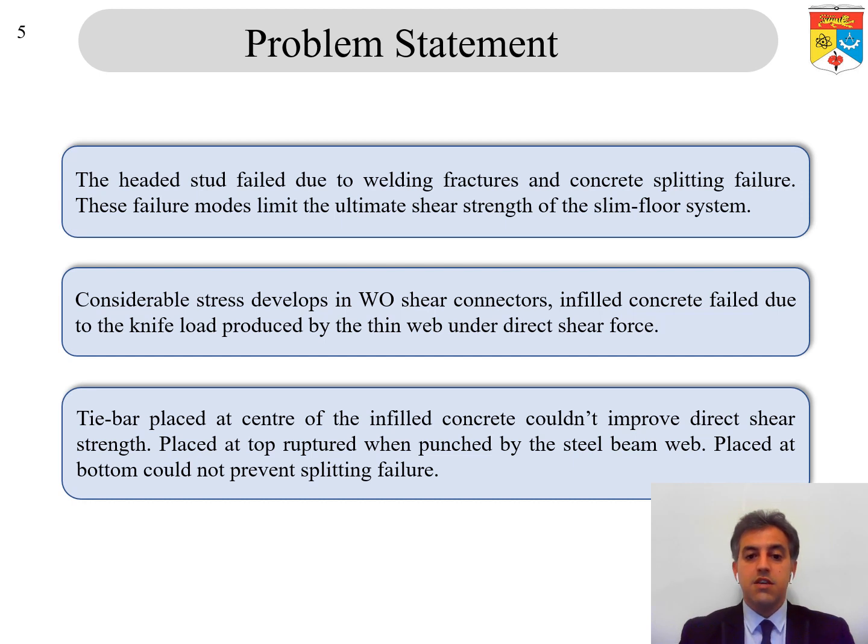Considerable stress develops in web opening shear connectors. Infilled concrete fails due to the knife-edge effect produced by the thin web of the steel beam under direct shear force.